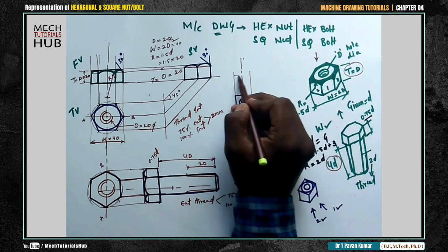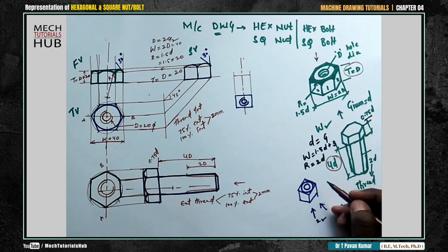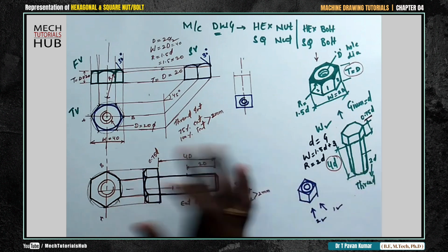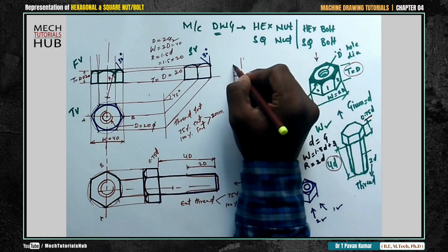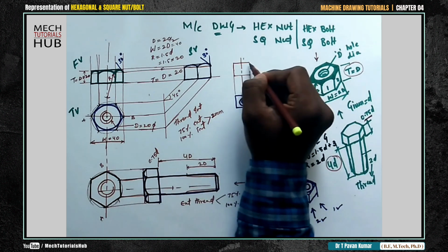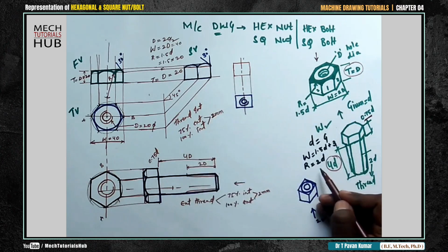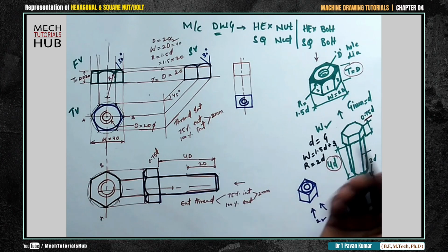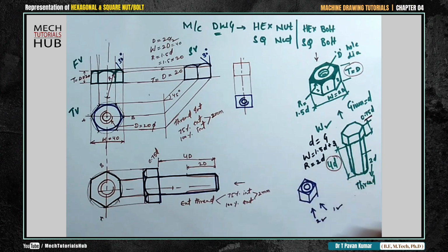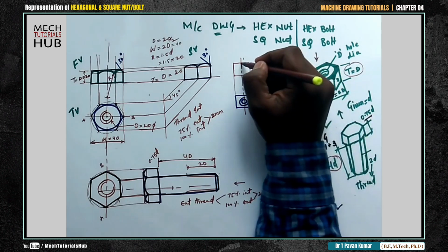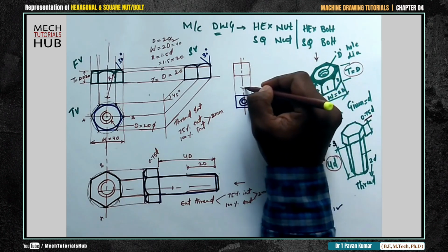I'll close somewhere here. Now, what is T? In this case, T is equal to D again. That is the similarity. From here to here, I'll make a mark of D. I'll just close the box. Now, what is R? R is equal to 2D. If D is equal to 20, R is going to be 40. From the intersection, make a mark of 40 somewhere here.